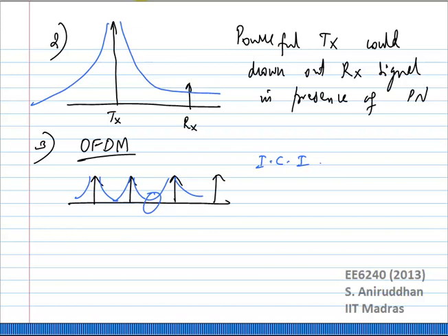These requirements aren't they set up by spectral mask? Spectral mask will define how much power you can transmit. Correct. So doesn't that take care of this problem? No, what do you mean by take care of this problem? If not for the presence of phase noise, you would very easily meet your spectral mask. The spectral mask is the requirement, right? This phase noise is the overall cause of why your RF signal could actually be drowned out. If not for the presence of this phase noise, what else could actually cause a problem at your receiver?